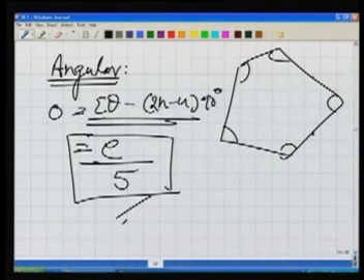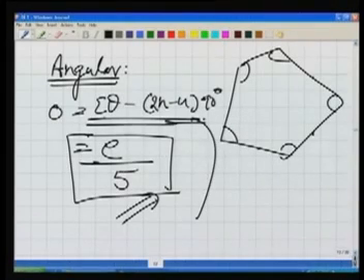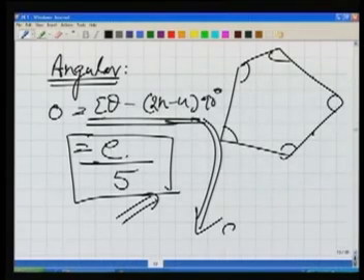If we apply this correction to each angle, what do we get? We get the sum, sigma theta minus (2n minus 4) times 90. In this case, after applying the correction for this error E, that will become 0. So angular corrections can be applied.